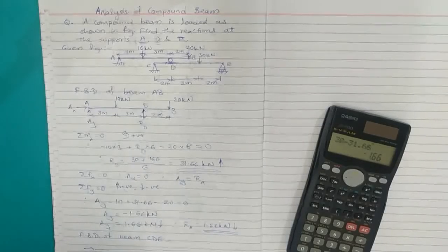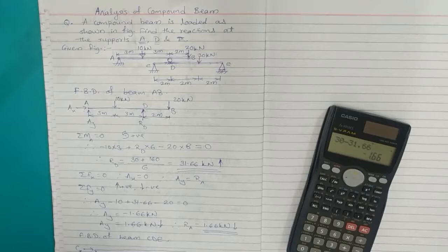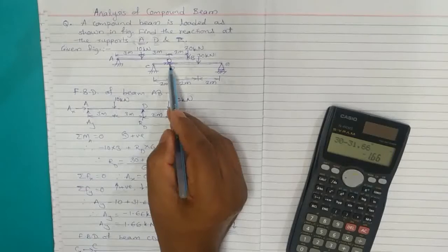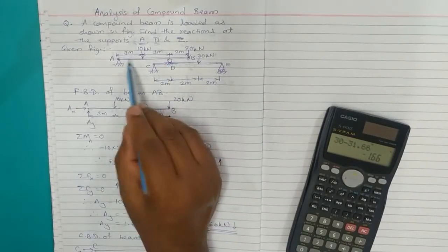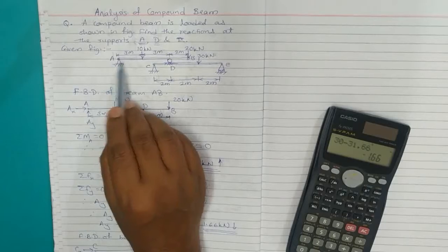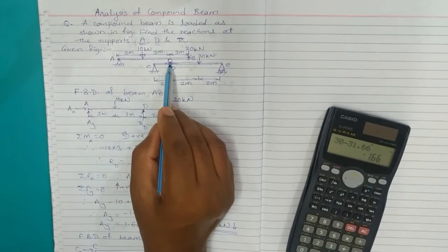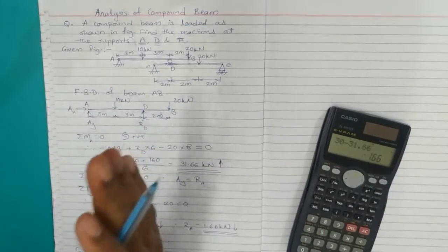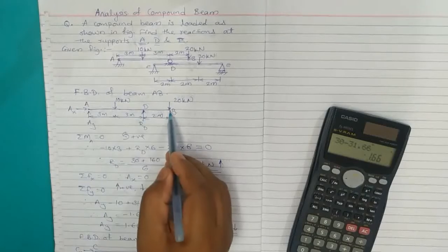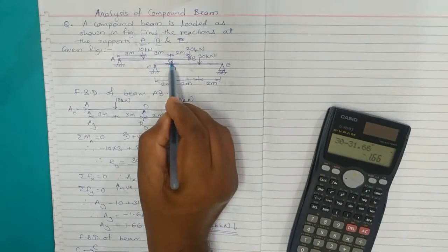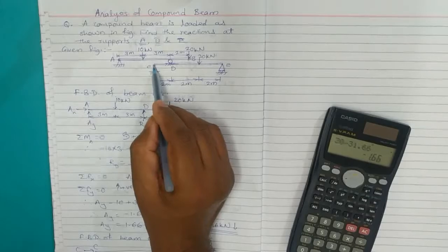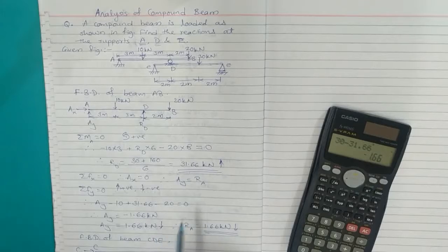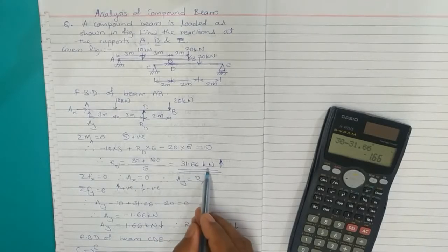At point C, again we can see there is a hinge or a pin support. Let's write CX, CY, horizontal and vertical components of that. At point D, now for the upper portion of the beam AB, this roller D was acting as a support. So we have shown a reaction going in the upward direction, which is representing support given to the beam AB. But the same roller now is going to act as a load on the lower part of the beam CDE. And this RD we have already calculated, which is 31.66 kilonewton.